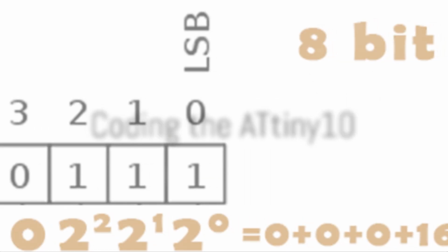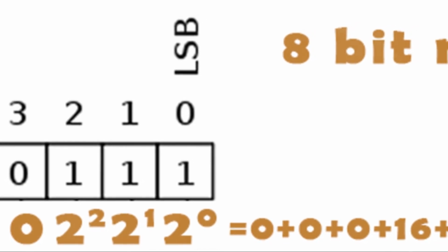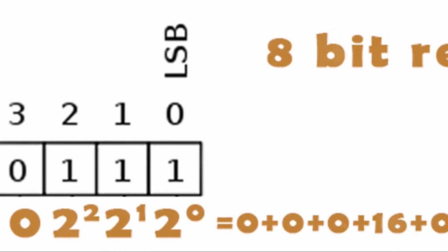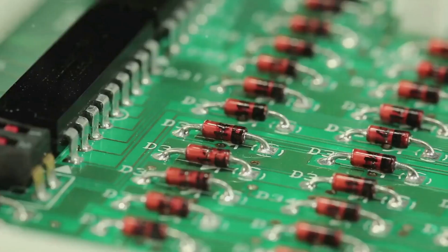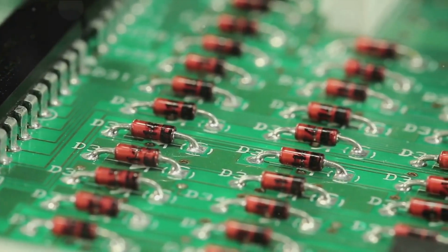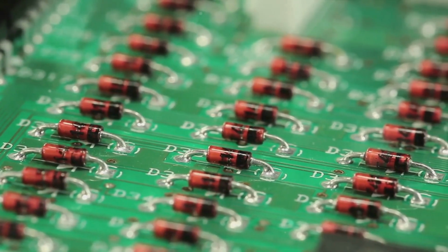Due to the limited RAM in the ATTiny10, you need to abandon many of the Arduino conventions and drop down to a lower level of programming. We call it register programming, which is just one level above assembler. This type of coding is not unique to the Tiny 10. It may be used with most any AVR chip, but does require a more in-depth knowledge of the internal registers of the particular microcontroller in use.